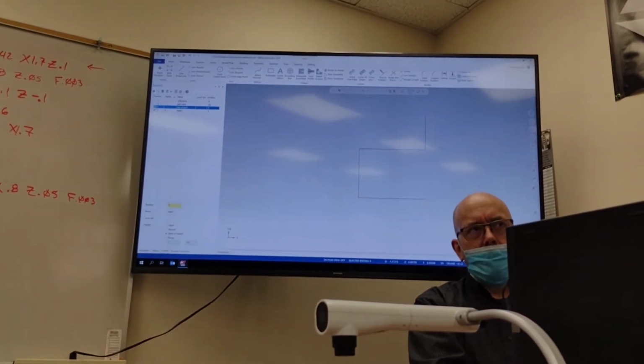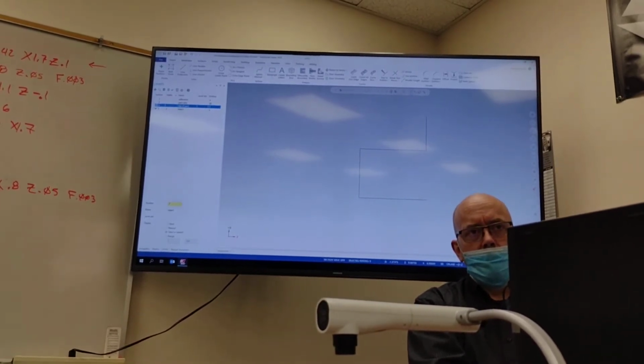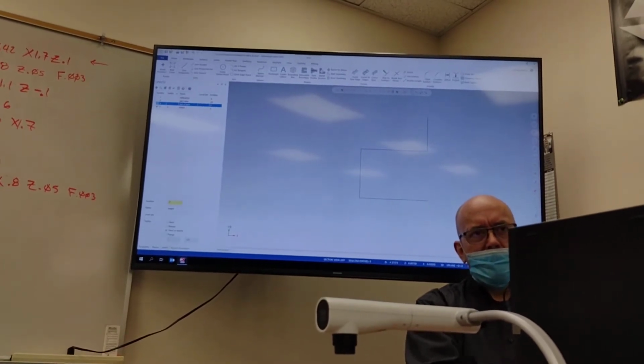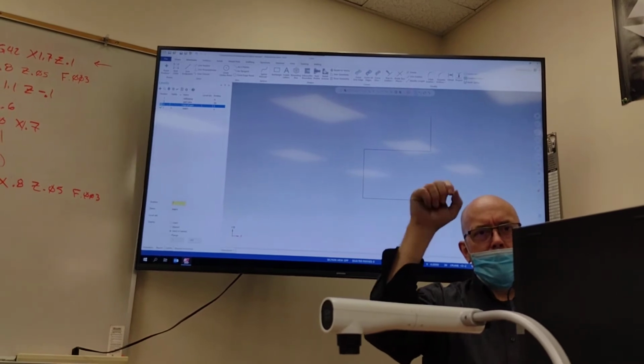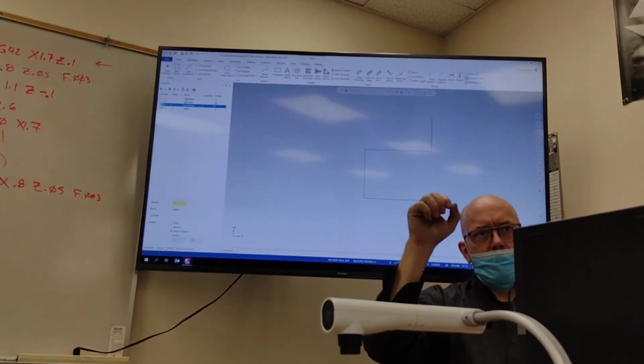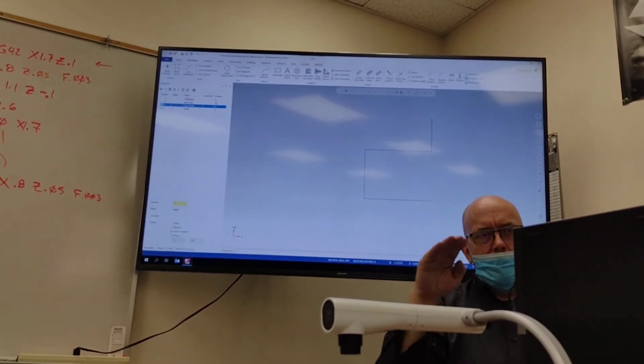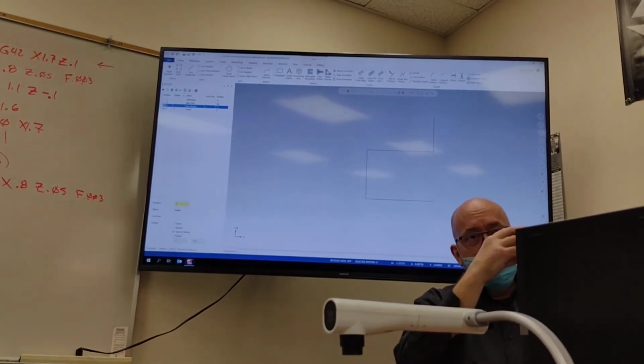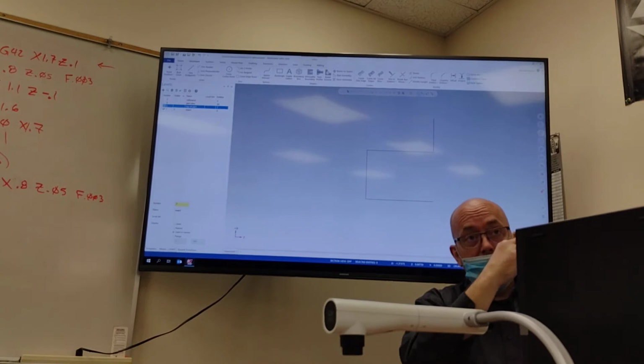Here's a fun fact of the day. You're familiar with knurling. Diamond pattern knurling is typically aesthetic, for tactile purposes, for handles and grips. Straight knurling is typically used to facilitate interference fits on two pieces.